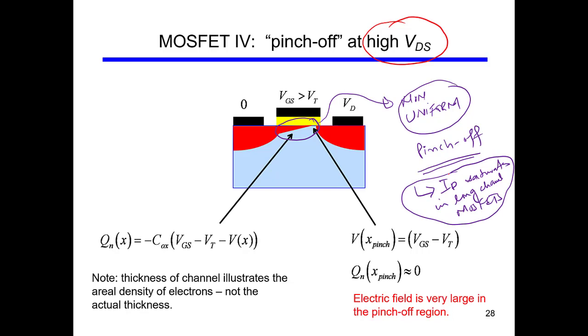So you see that when you apply a very high VGS, so VDS, so very high VDS on this side, then you can say that there is a sort of position dependent potential difference in the channel. So we have a potential difference in the channel due to this high VDS that is position dependent.